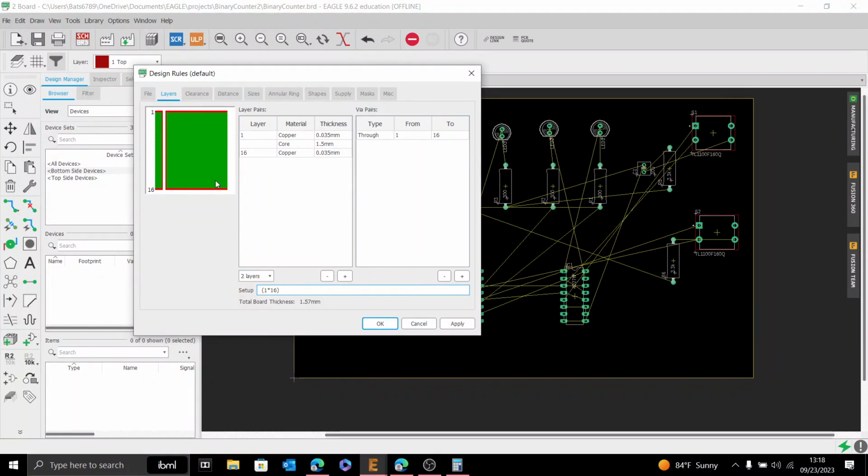And what is a layer in a PCB? Well, you guys know that for electricity to flow it needs a conductor. Ideally in this case we're using copper. And the layer is just a layer of copper. So 2 layers would be top and bottom. That's the simplest, that's the cheapest. Eventually you may get to where your board's a little more complicated. For this one I overdid it and did 4 layers. There was no reason for me to do 4 layers, but I did it because I could.